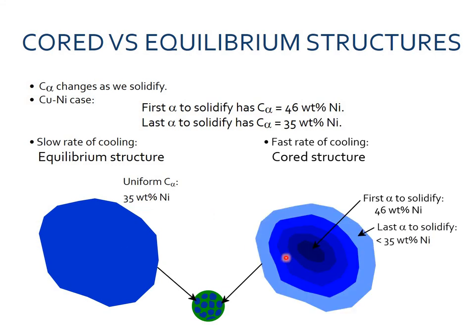So this is what happens once a solid nucleus is formed, and then nuclei after nuclei are being formed on the same first nuclei, but they are not properly cooled. The heat is not diffusing out properly at a specific rate because there is no time. We're not giving it much time in order that the heat is being extracted from the core itself. So this is called the cored structure. Okay.